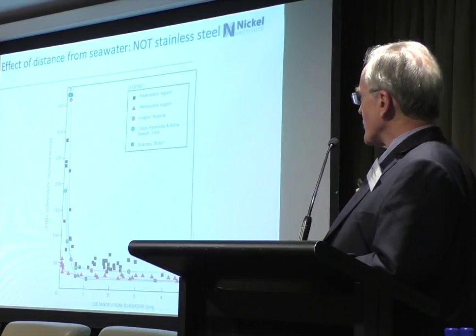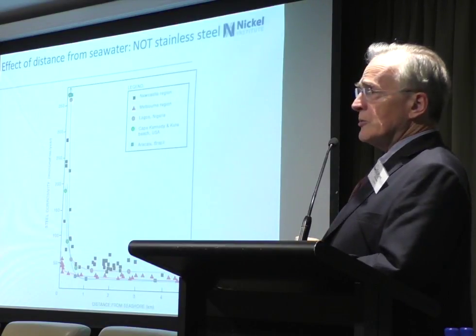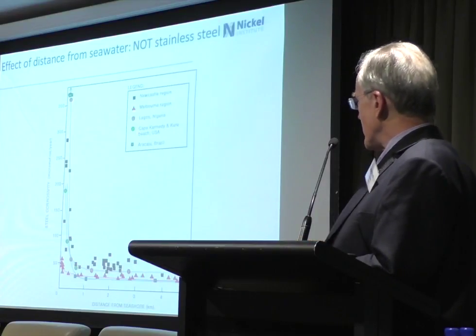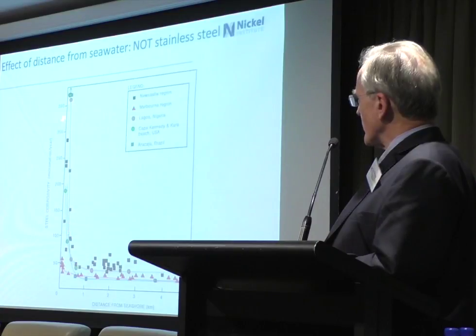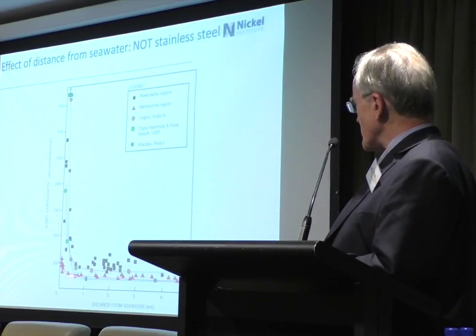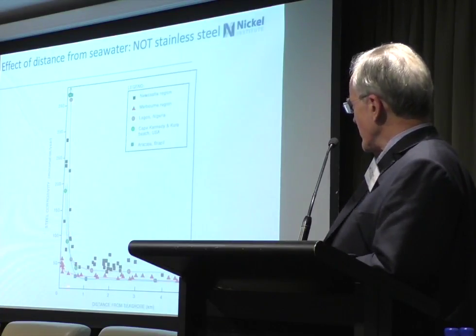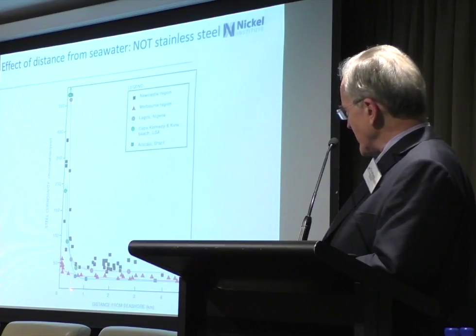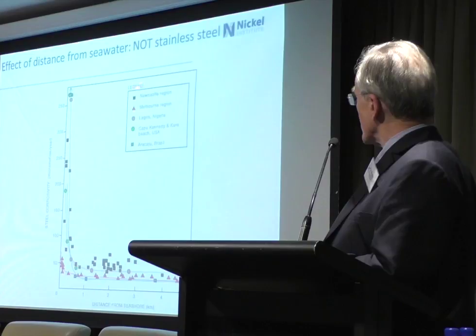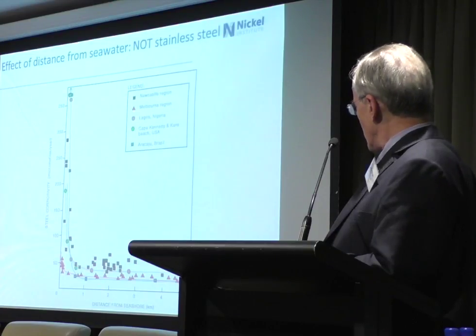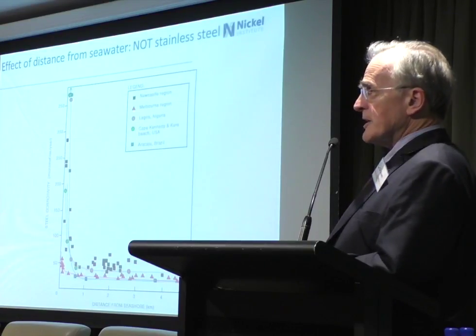And finally, let's talk about the oldest reinforcement of all. This is out of AS 4312, looking at the amount of chlorides you get as you come in from the ocean. If you're in Melbourne Bay, then you're down here and you're a couple of 100 metres in and there's nothing there. If you're in Newcastle, which is there, you're 4, 5, 6 kilometres inland.